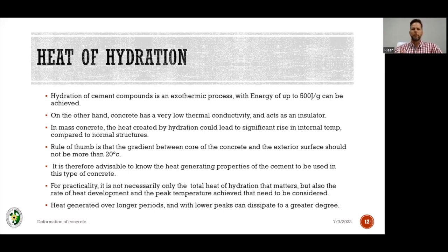So to put this into a timing perspective, your concrete truck is batched in about 10 or 11 minutes, depending on your batch plant processes and optimizations. That's typically how long it takes to get that truck filled up completely. Some of these plants are quicker. So if it's about 10 minutes, you know that your concrete plant has the capacity to batch about 60 cubic meters of concrete in an hour. Or even less, let's use 6 minutes as an example. But let's park that idea.